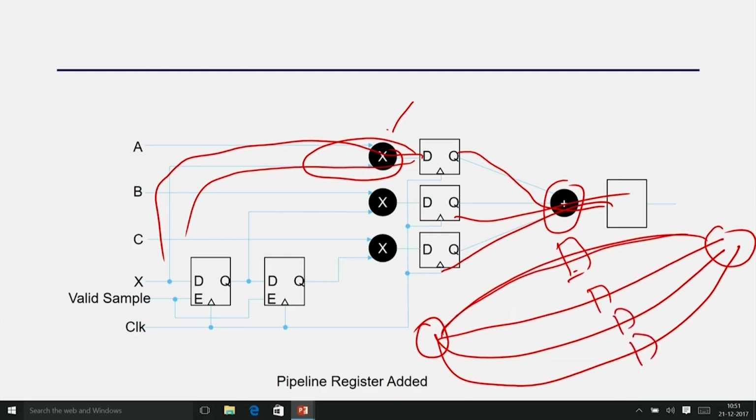Even if there are 4 multipliers in this path and the other paths are simpler, say with only 1 multiplier, you cannot just say I have to add latency, I will add it here and I am done. That is wrong, because if you add 1 latency here, this data will be delayed by 1, but the other data will all come in earlier. Then it is not synchronized.